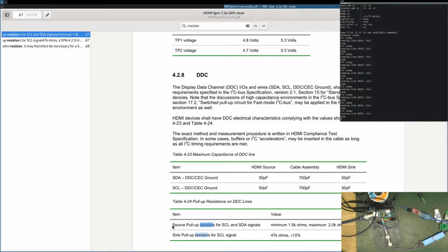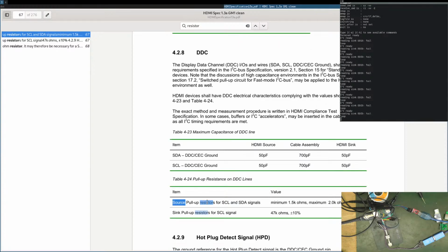The source pull-up. So normally on I2C, you only have one side which pulls it up, and not both sides. Okay, so I have a flaw in my design. Kind of. No, sink. Okay, yeah. So I have a flaw in my design. Oh, not too important, but actually I don't know. So they also have a flaw in their design. The original guy, which it's the research.